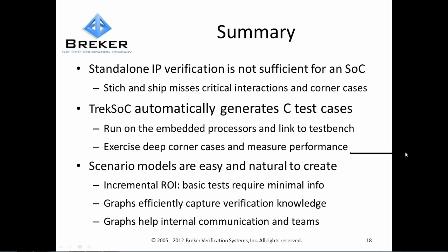We did not go after the UCIS API. Instead, we went down a path of exporting stub SystemVerilog files that define the cover points and trigger them the right number of times. This allows you to run that SystemVerilog once and pick up all the coverage from the tool in your existing environment without needing integration from it. In fact, we did this on Cadence's recommendation.